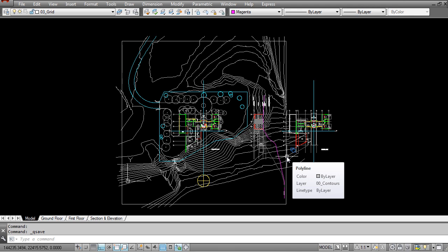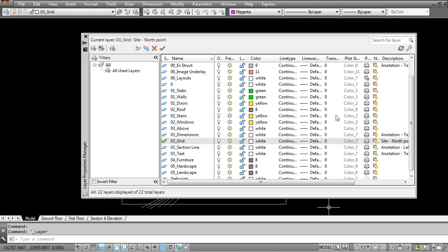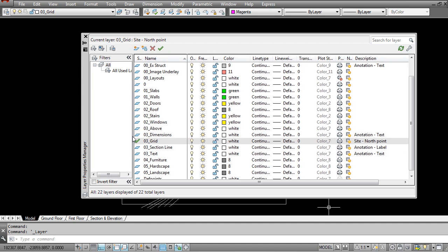So you can maximize the layering manager in 3D for all of your 3D layers. So here again, I'm bringing you to the point where you don't want to mix a 2D object and a 3D object on the same layer when you're working in 3D. You want to be able to completely turn off your 2D geometry as you're working and developing your model in 3D. So all of this has to do with setting up your layer manager in AutoCAD before you actually export your plan and use it for modeling in 3D Max.